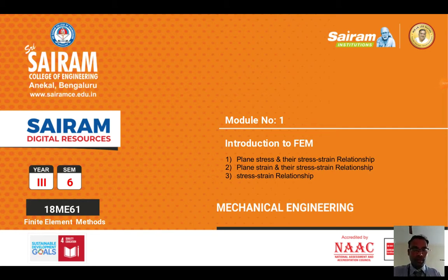So, in this PPT, I'm going to tell you about the concept of plane stress and plane strain, and what the stress-strain relationship is for both cases. Normally, plane stress is represented by a very thin plate. In the XY direction, the plate is subjected to an in-plane load, along the X or maybe Y direction, and no load along the normal to the plane. Such a problem we are going to call a plane stress problem.